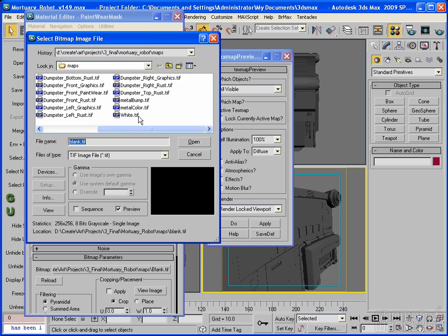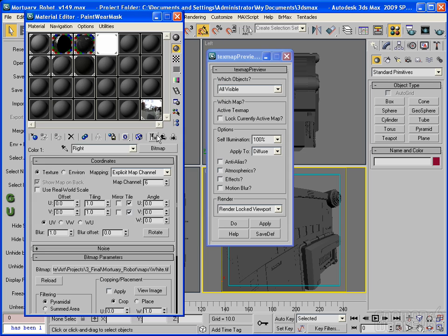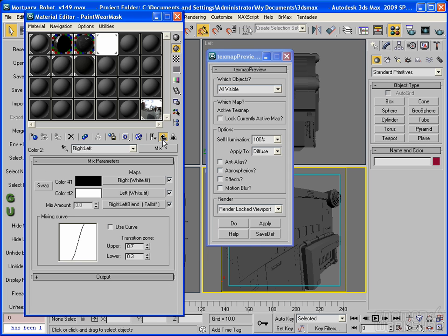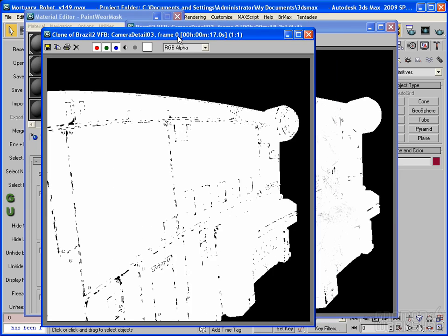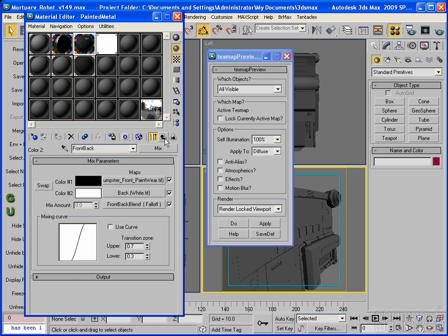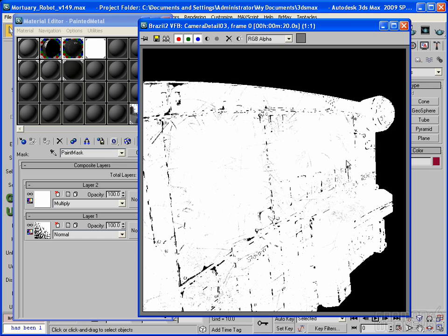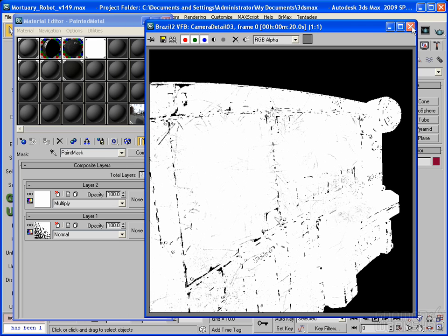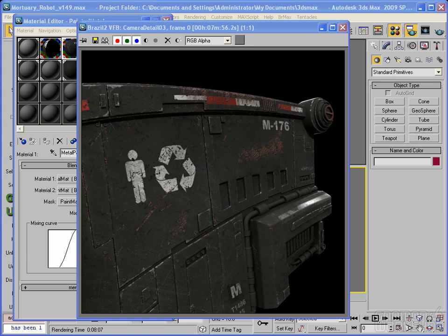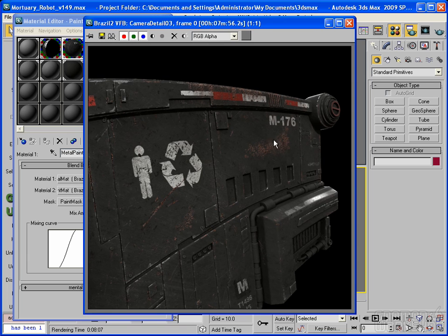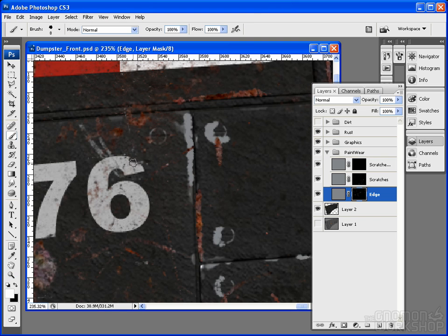And so I grab the new map. Now there it is, the black and white specific map along with the black and white procedural one, and then I do a multiply. So the two maps together form the combination of the specific stuff you painted and the more general procedural. So now when you render it, you see it's merging both together. So there's lots of areas with the painted parts and areas with the more procedural stuff.